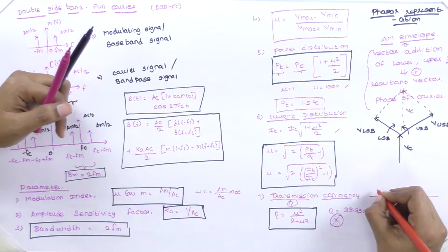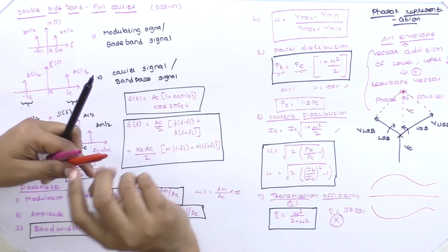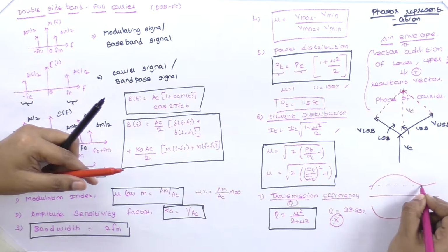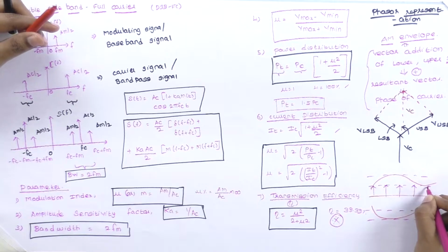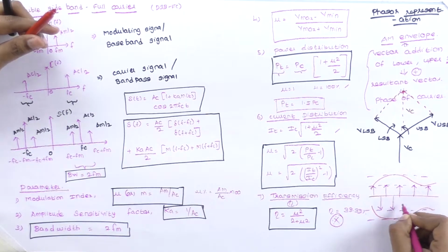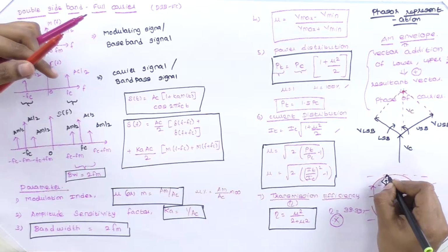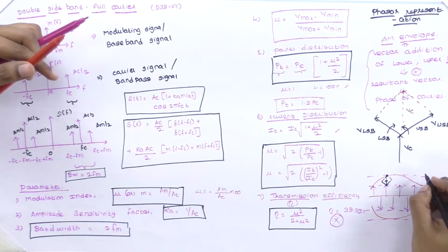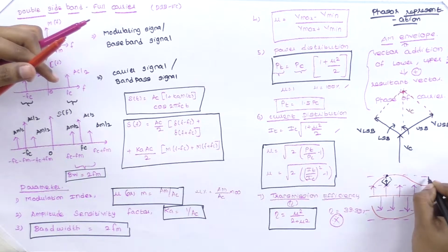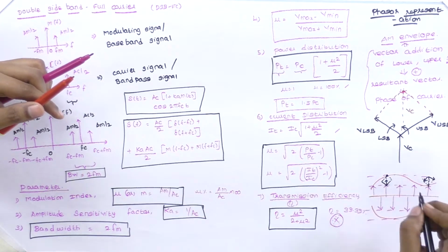If it is in a signal, we can identify it clearly. See, this is our amplitude modulated wave, and this is our V minimum, and this is our V maximum. So, our vector addition will look like this for a maximum. This envelope is identified as a result of vector addition. For the V minimum value, it will start like this. It may be in phase in some places, and out of phase in some places.